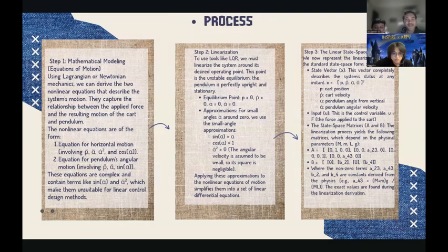Okay, so now the process. Step 1: mathematical modeling, the equations of motion. Using Lagrangian or Newtonian mechanics, we can derive the two nonlinear equations that describe the system motion. They capture the relationship between the applied force and the resulting motion of the cart and pendulum.